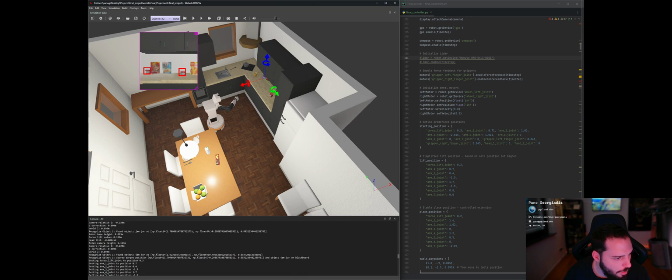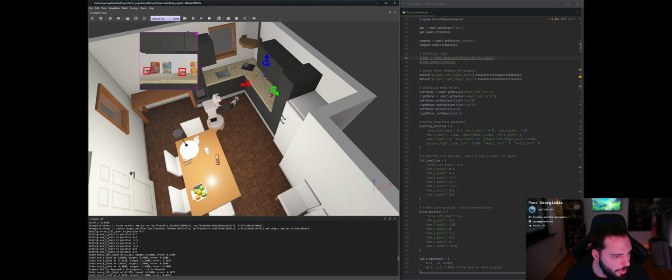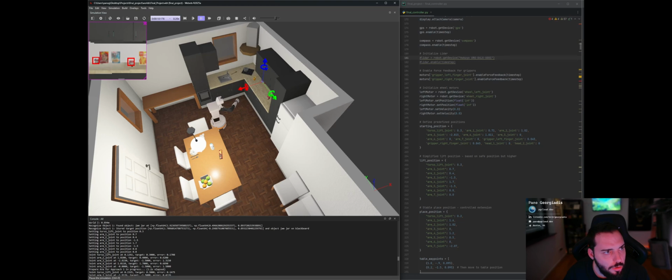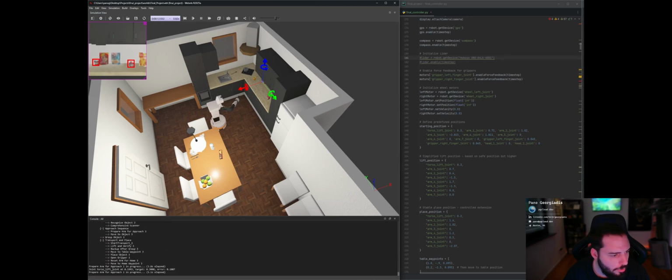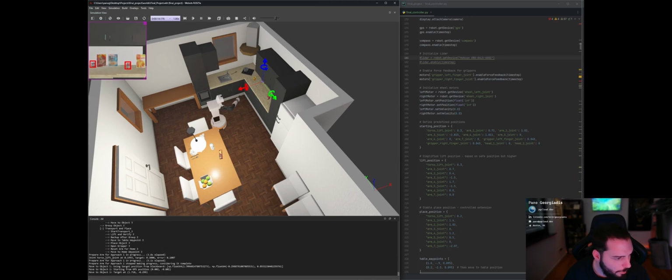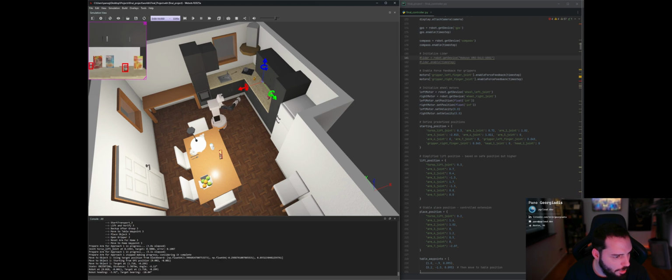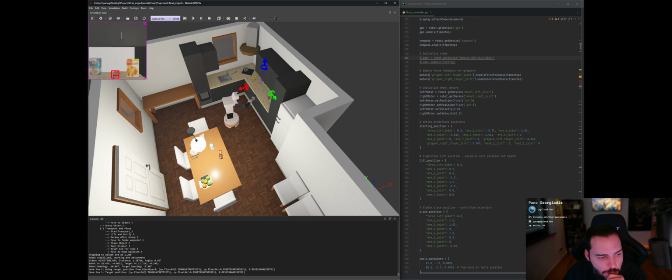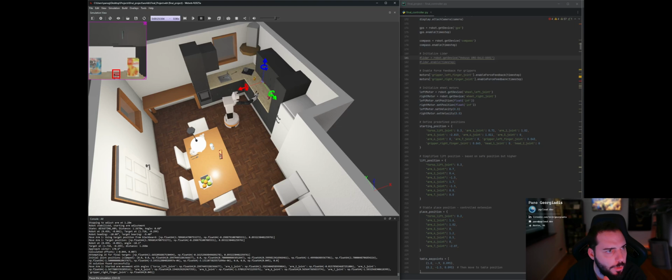So, stored target position and object jam jar on blackboard. It will then go into the prepare arm to move to object position in order to calculate inverse kinematics from the same position each time, using target position from Blackboard and starting GPS positioning in order to move to waypoint. Once it gets to that 1.23 meters, it should start calculating the inverse kinematics, which it did successfully right here.